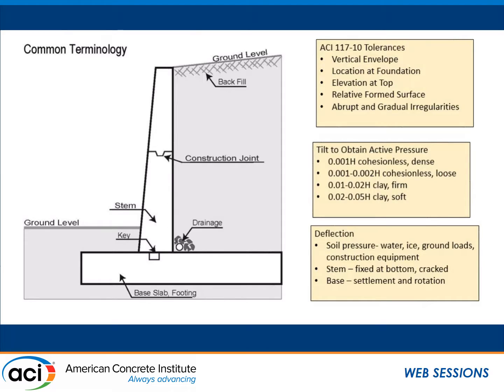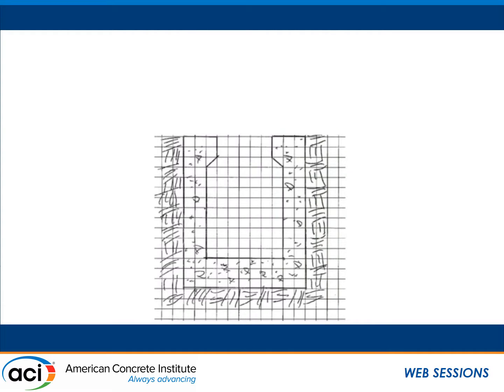And then it's the question of, is the stem wall cracked? Is it gross moment of inertia? Or I love the ones that use gross moment of inertia and decide it was fixed right here at the bottom. There is no base rotation. It's fixed. And I'm like, well, I don't know. Once you get a number, I'll figure out whether that's good or bad, but I don't really think that's the right way to look at it either. So when you think it's goofy, sure enough, when somebody has an issue, you will find somebody to make a deflection calculation. I really think it would help if we had something in print that says, this is almost like guessing in my view, but we've been here.